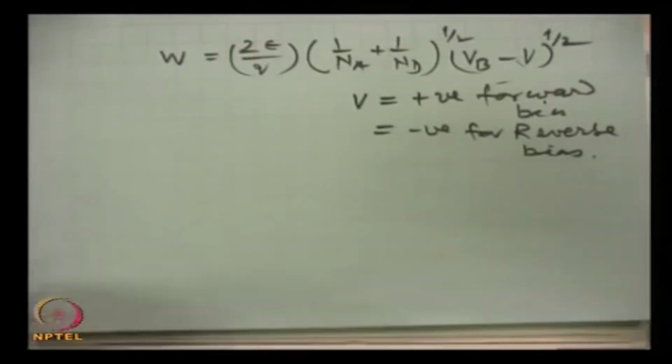We can also discuss how the currents flow in the forward direction through another useful description in terms of another diagram. We should take note of one thing, that in devices normally asymmetric doping is used. That means doping on the P side and N side are not equal. One doping is much higher as compared to the other.